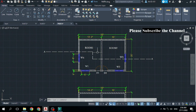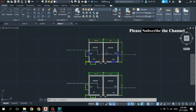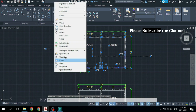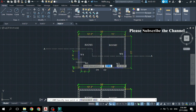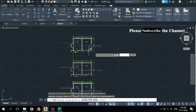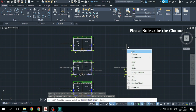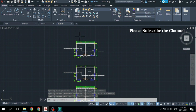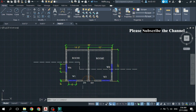It is very important to make a copy of your 2D plane. Simply select all of them and right click and then click on copy selection and specify the base point. Let's click at this corner and go upward or downward and click here. Now you can see it is the copy of that, and then press enter to finish the command. Now you can see it is copied here, so you must copy it.